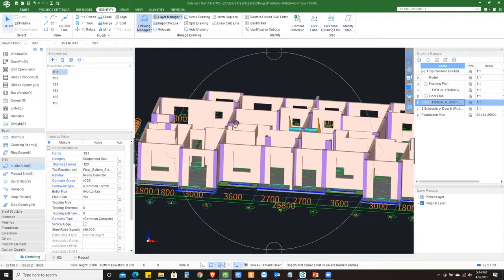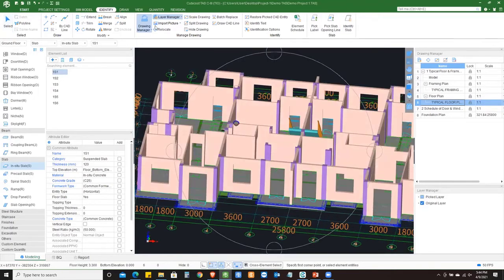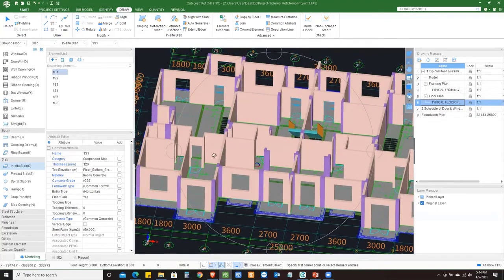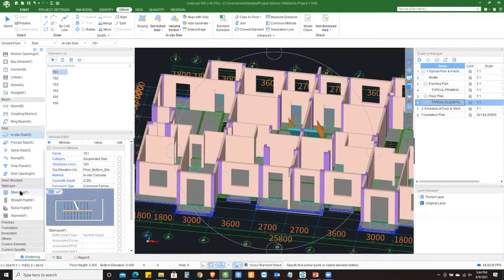You want to create different shapes. You have different shapes under the draw tab. You have the arch shape, spherical shape, conical shape, sloping, variable section, which really goes handy with the sunken slab. So different information tools are there, not going into details because the time wouldn't allow us to do that. Okay, in terms of staircase, you have different options as well.